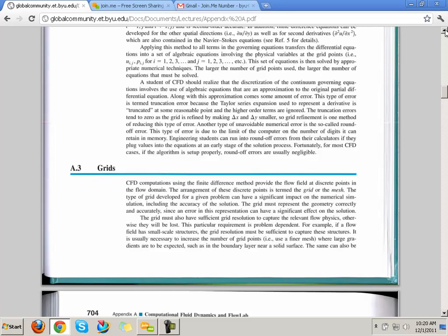So when we mesh, like in lab, if you zoom in really close on the mesh that you create, you'll notice that there's a tet mesh in the whole filled space. And then there's also another mesh that's usually a hex mesh that's real thin. It's a boundary. It's a certain number of layers thick, and it goes around the object that the airflow is going around, because that's where you have a lot of boundary effects of the fluid flowing past it. In fact, when you set up the mesh, there was a place where you told how thick the boundary should be. And I mentioned in lab yesterday it should be at least 6 layers thick.